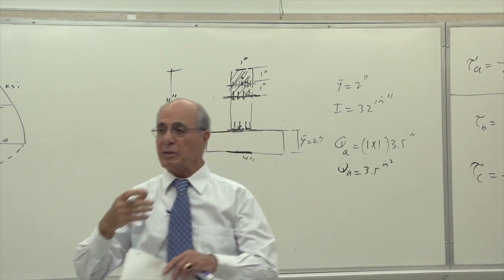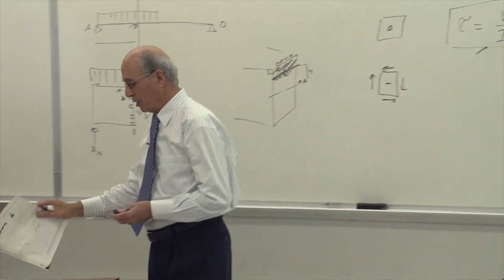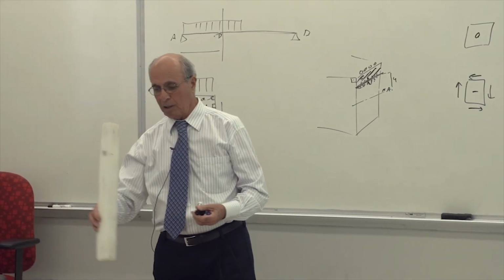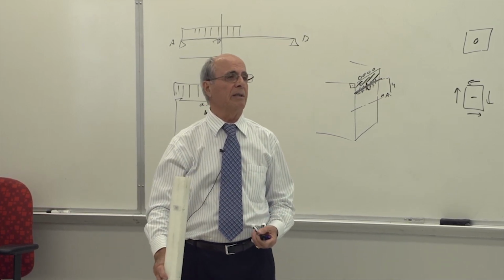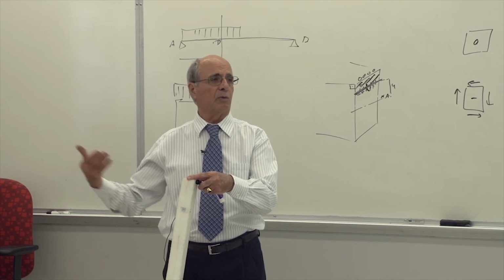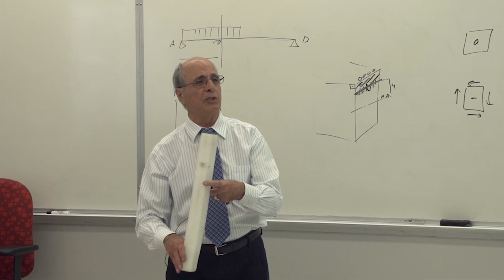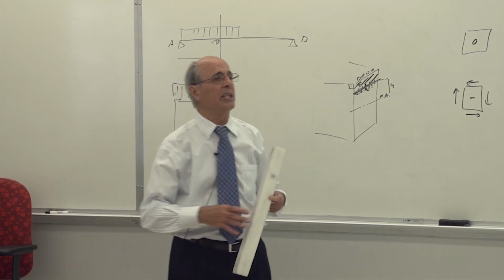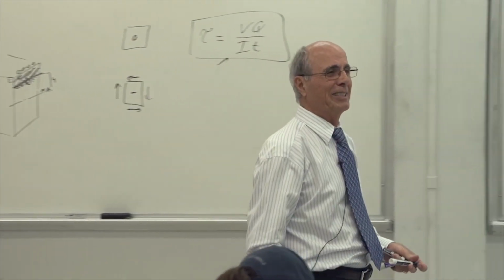So if you have an item like that, it's obvious. This is logical. Actually, this is what happened to the building as well. You have a column sitting on a foundation, which is much bigger. Is that correct or not? And if the horizontal force comes like earthquake forces or wind forces, where do you think the column is going to shear off? It's going to shear off at its base. There is no reason for the foundation, which is much bigger in thickness, to shear off. Everybody understand that?